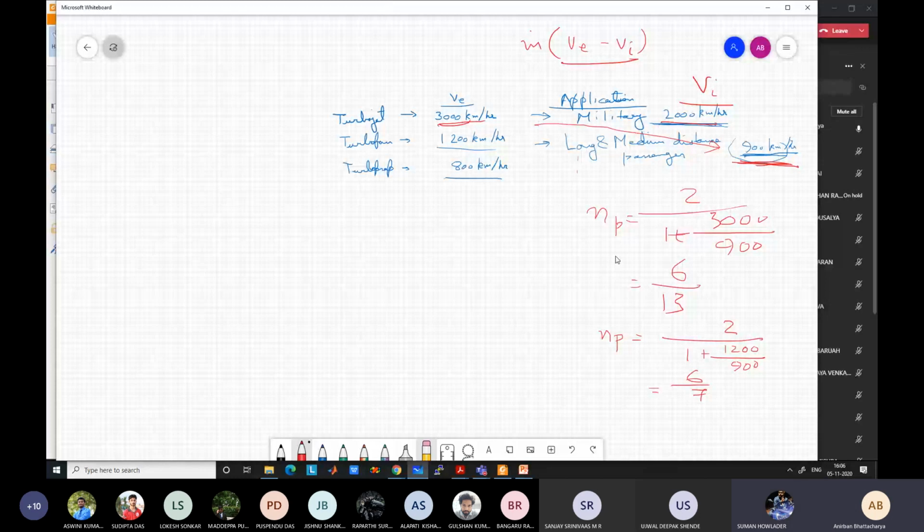So you have to think in terms of loss of kinetic energy. Although it is generating a huge amount of specific thrust, most of it is just getting lost to the atmosphere. Only a small part, or half of it, is being used for moving the aircraft forward. In this case, very little is getting lost to the atmosphere. But the specific thrust is low for this turbofan engine.